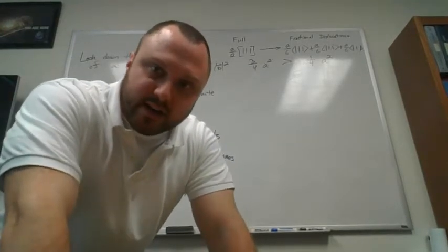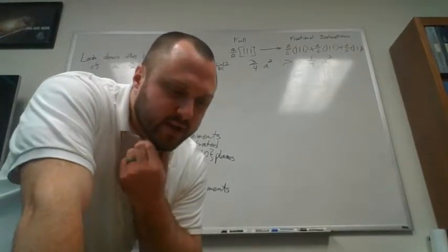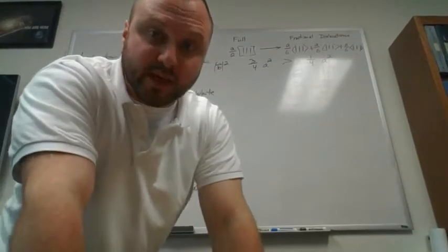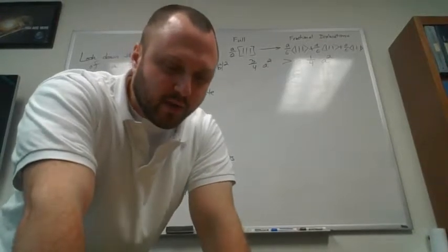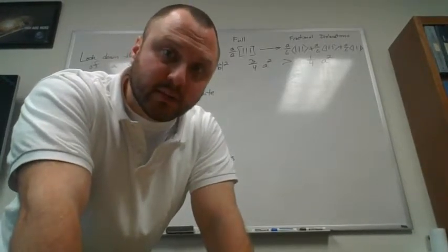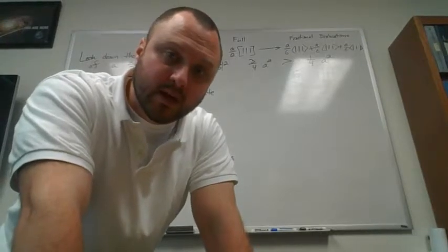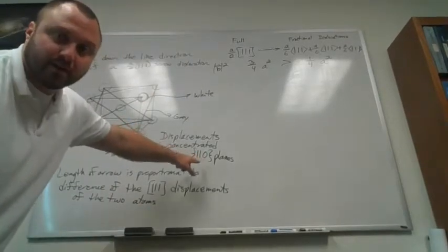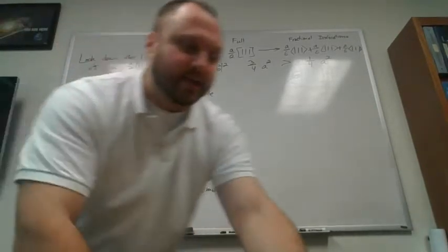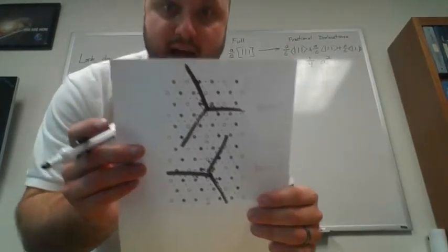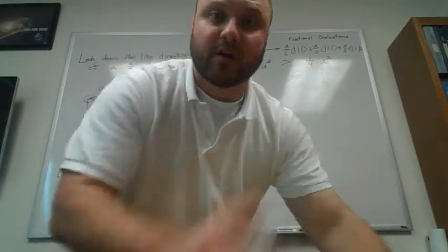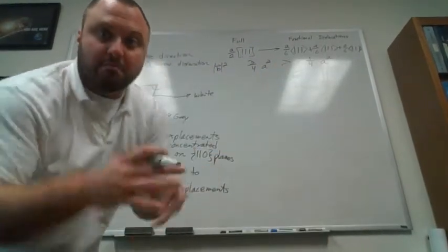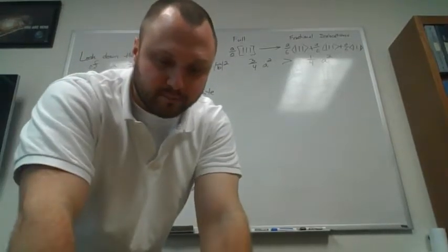So this process is kind of wacky and a little bit hard to visualize, but it's called threefold splitting. We have a dislocation that doesn't break into two, it breaks into 3 fractional dislocations. And the really important thing is it gives us a 3-dimensional dislocation core. If you look at where those 110 type planes are, they're coming out of the page that you're looking at in this figure at different angles. They're not all parallel to each other. So that means that these new dislocations are all in different directions. We have a 3-dimensional core.